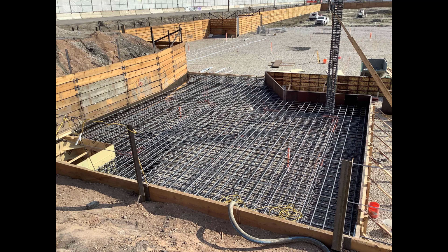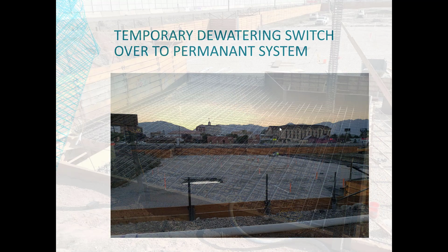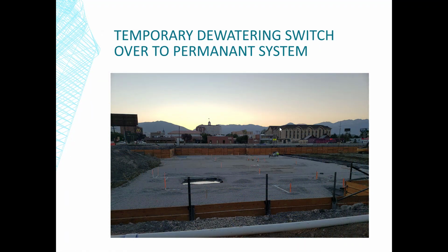So then starting back where they've already finished, starting to put in the rebar. So one of the things I wanted to talk about was as they go over to the permanent dewatering system, they've got these depressed areas for maybe thickened footings or something like that, or maybe this is the elevator pit, probably an elevator pit. But the dewatering system's not below that level, the bottom of the elevator pit, so they'll probably have to pump this out. But you can see that it's starting to collect water.